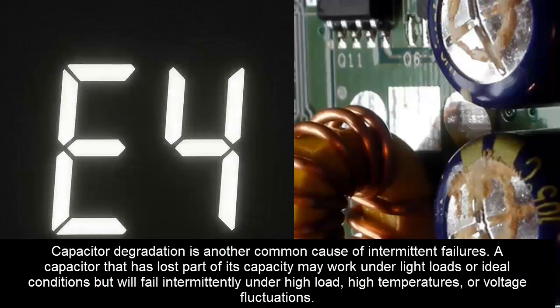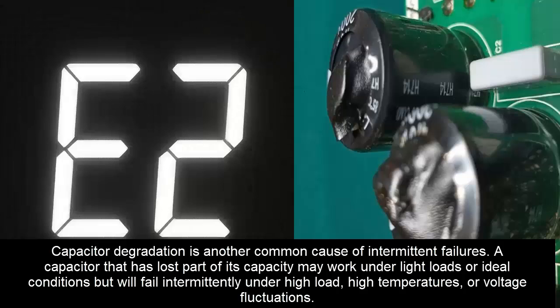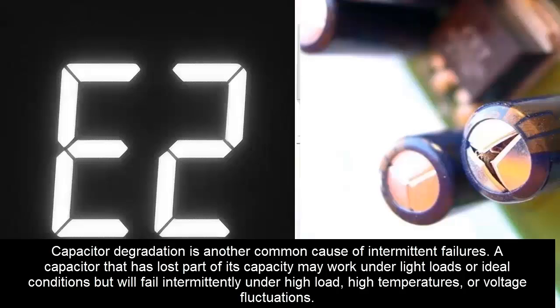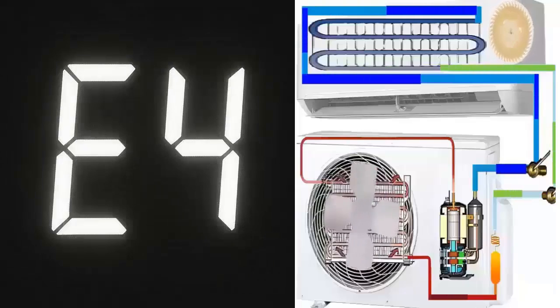Capacitor degradation is another common cause of intermittent failures. A capacitor that has lost part of its capacity may work under light loads or ideal conditions, but will fail intermittently under high load, high temperatures, or voltage fluctuations.